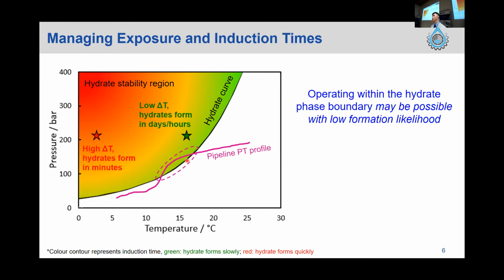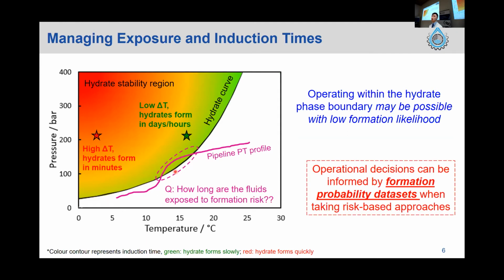We want to ensure that hydrate induction time is much longer than your residence time. And then we can be more confident that you can operate within the hydrate stability region without any risk of getting hydrate plugging.